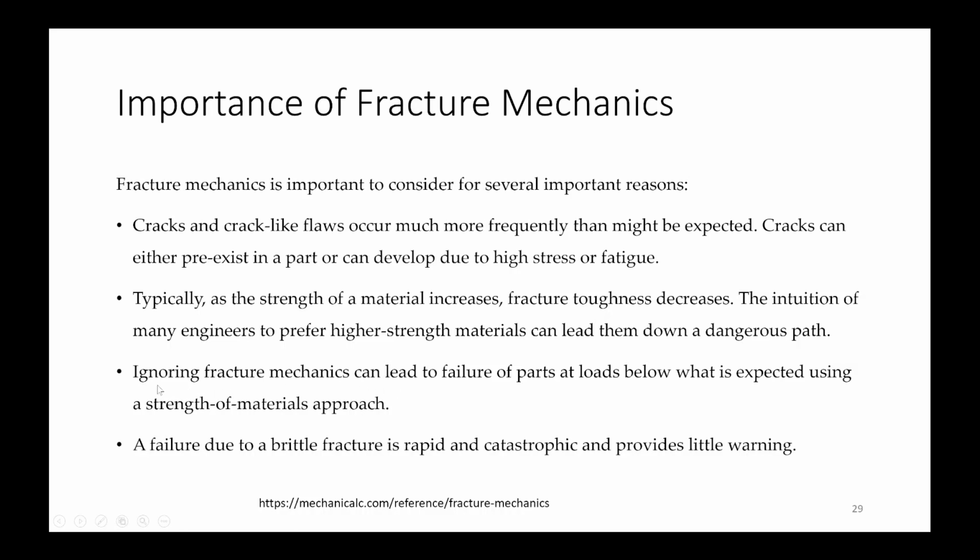Ignoring fracture mechanics can lead to failure of parts at loads below what is expected using a strength of material approach. A failure due to a brittle fracture is rapid and catastrophic and provides little warning.